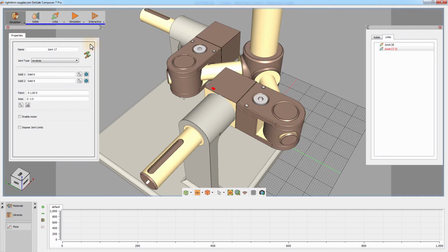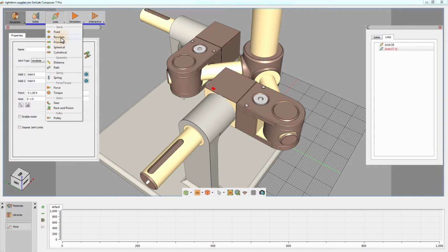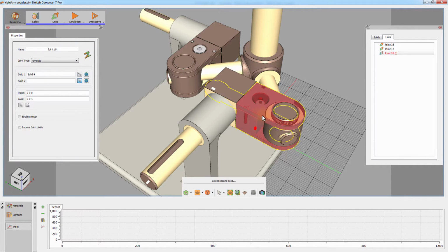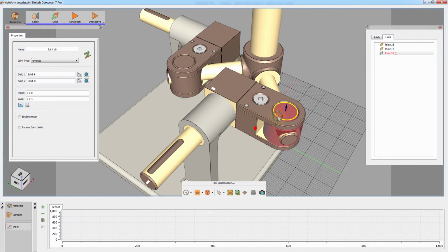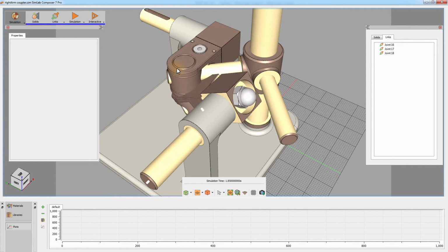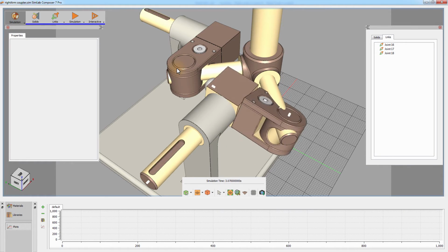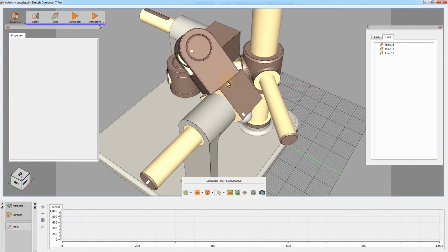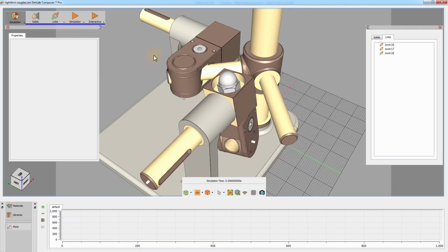To connect the pivot to the bolt component, create another Revolute joint. Select the parts as solids and set the axis of rotation to this joint by clicking on the curvature of the pivot on the z-axis. Play the simulation and notice how the pivot is rotating along with the rod, yet it has the ability to rotate around its axis due to connecting it using a Revolute joint.